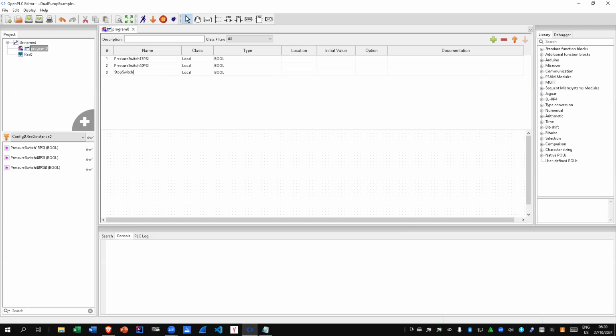The first one is a stop switch, which is normally closed, and this is assigned as an input. Part of this is also connected to the other side, the mechanism to power the compressor, so that we can remove the input power to the compressor if need be. This one is just for monitoring if the switch is actually pressed or not.